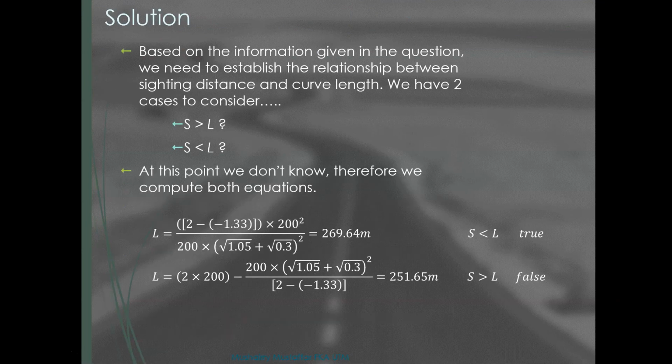Based on the information given in the question, we have to establish whether S is greater than L or S is shorter than L. But at that point we don't know. We were not told. So as I was mentioning earlier, we have to compute both equations. Let's look at S less than L. When I put all the numbers in there, P, Q, and SSD, I obtain 269.